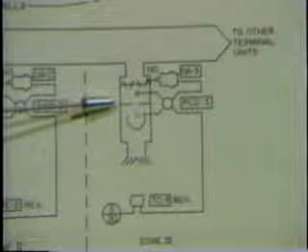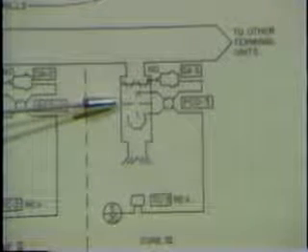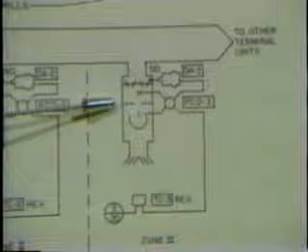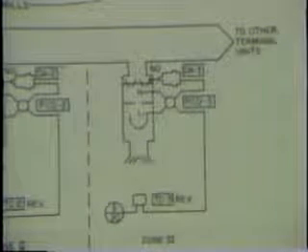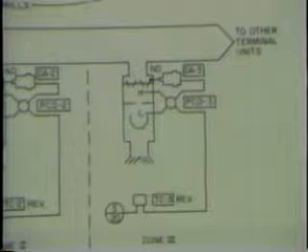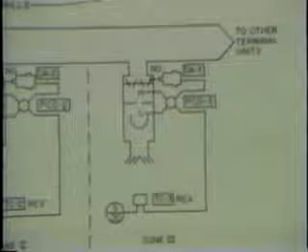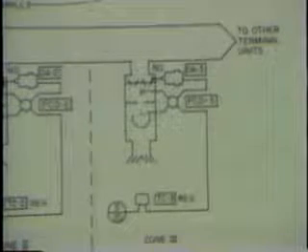The purpose of the submaster is to compensate for changes in flow that may result from changes in duct static. Heating is not available from these systems, since they are cooling only. They serve interior zones only. If some means of overcoming the heat loss through exterior building walls has been provided, these systems may be applied to exterior zones.